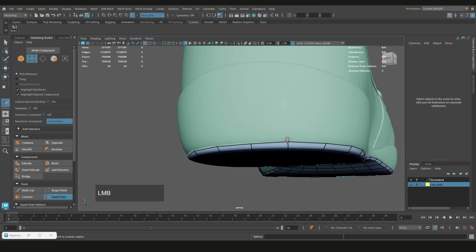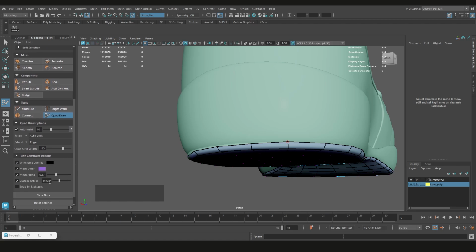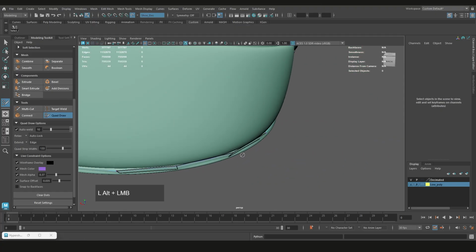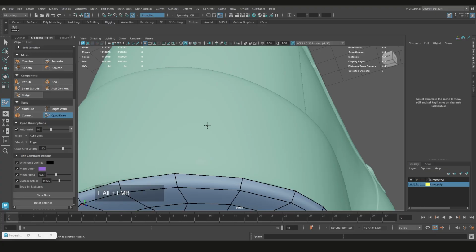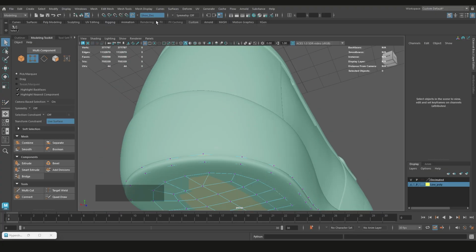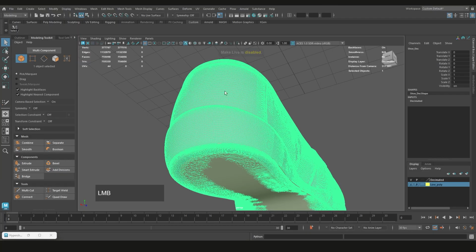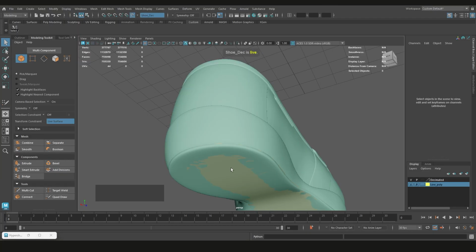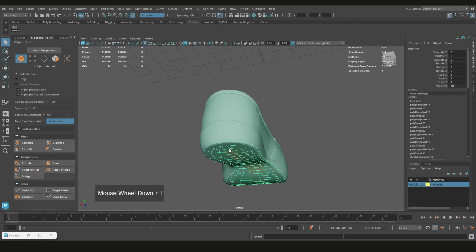And what people also like to do under the modeling toolkit over here under quad draw options, the live constraint options, all right? The surface offset, I have this at 0.035, which means the distance from this thingy here to this live object, right? Remember this piece here, we made it a live object. So the shoe here, object mode. This shoe here, we made it a live object, right? This piece from here to there, that's what it's doing. It's showing you the distance.